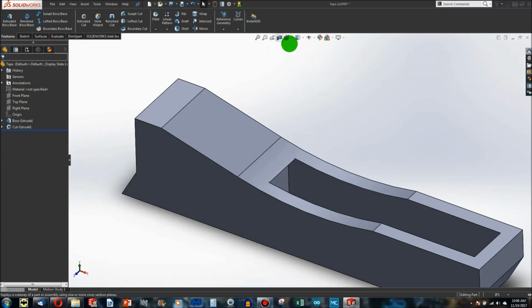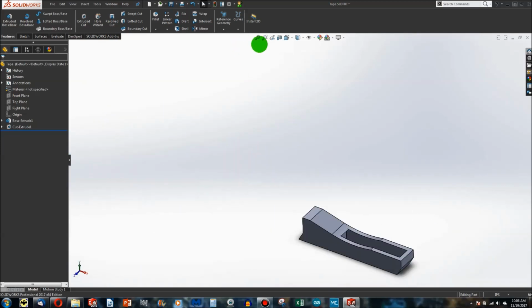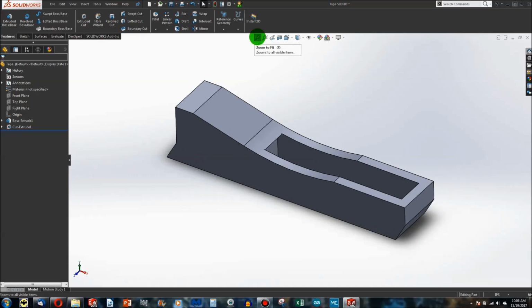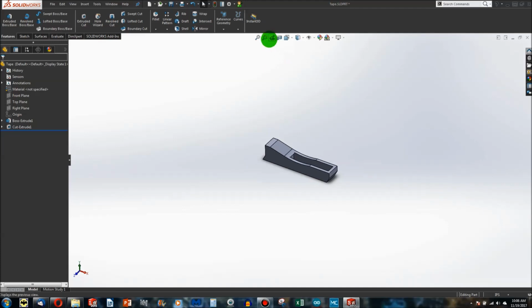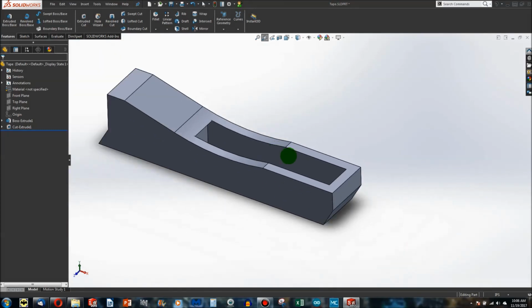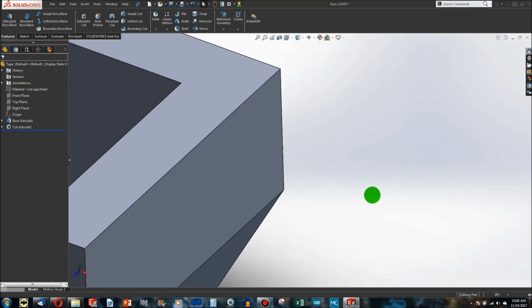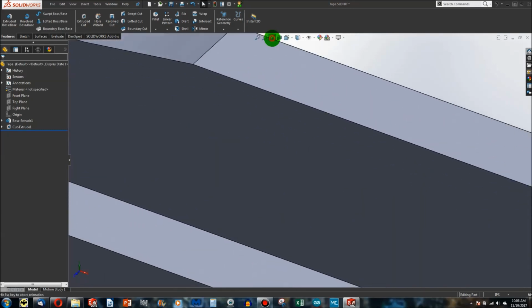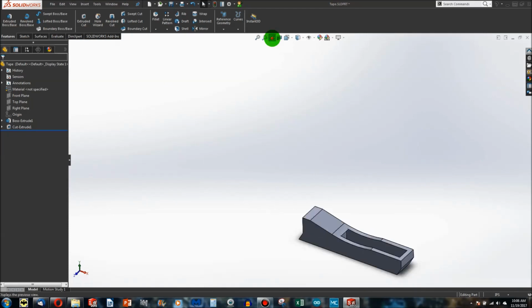Well, I have certain view controls up here that will come in handy now that we've got solids. The first one is zoom to fit. If I've got a solid way out here, I can click this zoom to fit button, and no matter where or what orientation the solid is, it zooms to be the perfect frame. I can also do a zoom to location. So I click this button, draw a little square, and it zooms to that little square that I choose. Pretty simple. And I've got this button, which just takes me back to the previous view. Again, very handy.